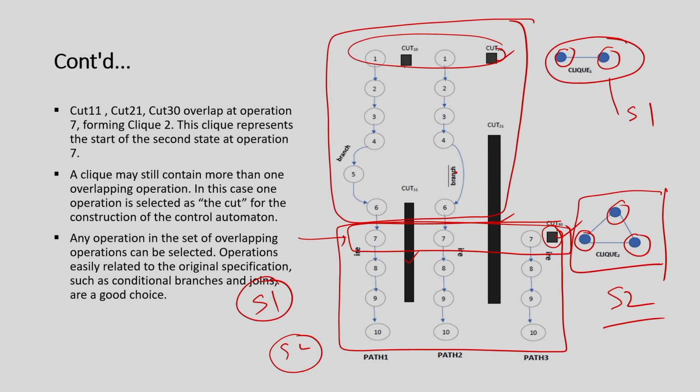but I am going to conclude today with this note: I will take the behavior, identify the CDFG, identify all the longest paths, and for each path identify the minimum number of states needed. Then I am going to combine the states of all the paths together. For both problems, identifying the minimum number of states for a path and identifying the minimum number of states to satisfy all the paths, the problem is solved using the clique partitioning problem.